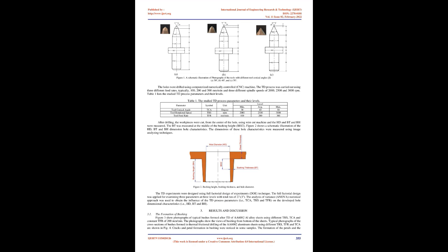Ozek and Demir 12 investigated the TD of 4 mm thickness A1050, A6061, A5083, and A7075 alloy sheets with different thermal coefficients of conductivity. The generated frictional heat, surface roughness, and BH according to TFR, TRS, and thermal conductivity coefficient of the materials were investigated. The results showed that, at the high TRS and low TFR, with increasing thermal conductivity coefficients, the frictional heat was increased. The greater BH were achieved at lower TRS and high TFR.